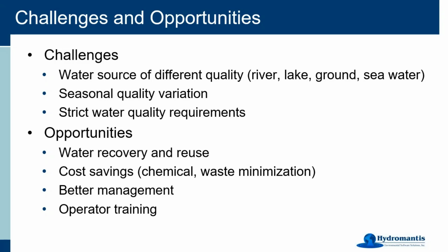The other part is, of course, directly related to cost savings. As I said, water treatment plants are more chemical intensive, so the more chemicals we add, we can get better treatment, but it also leads to other problems, for example, a lot of solid generation if you overfeed your chemicals. So essentially, there is a chance to optimize and manage your system in a better way.